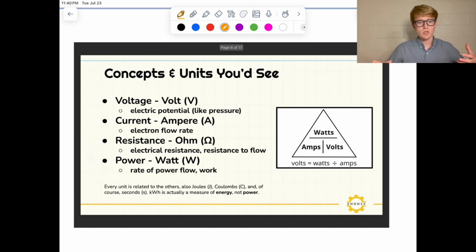And we want to think of voltage like pressure in our water flow analogy. So I might have a sink where the water is flowing really fast. There's a lot of pressure. That might be a good analogy to voltage, just pressure in a pipe. Okay, so then current is going to be flow. So how many electrons are flowing through my circuit? In our water analogy, how much water is flowing through my pipe. Now the other thing I want to say about current is that current occurs when we have a difference in potential. If I have a potential difference, that is when current will flow.